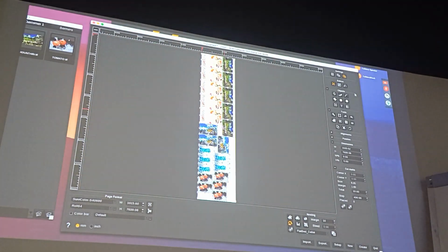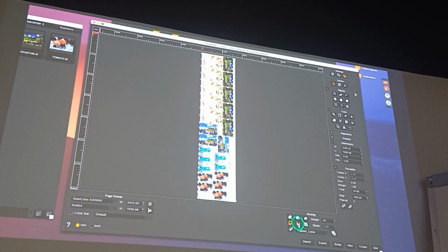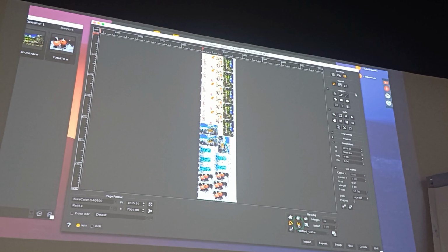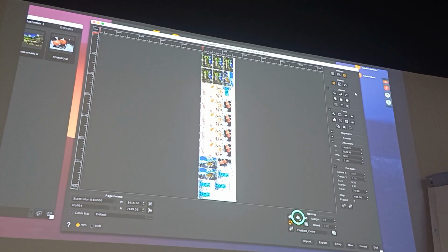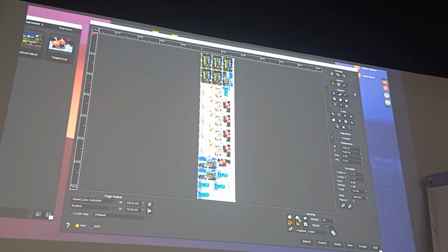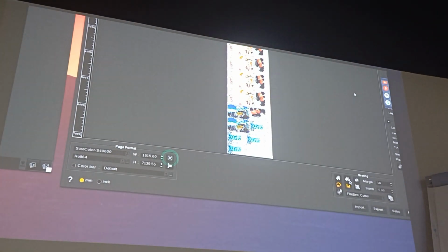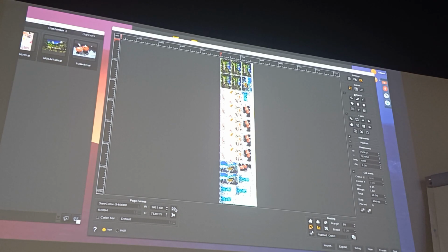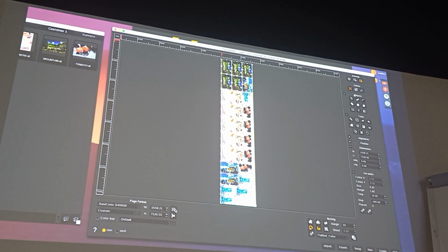You can also activate this option in order to create independent rows to ease further manual cutting. To update the nesting, click the Nest button again. As you can see, files are now organized in rows. Before exporting this layout, I recommend you crop the size of the document according to the nesting by clicking this button. This will allow us to add further marks from the print module if needed.